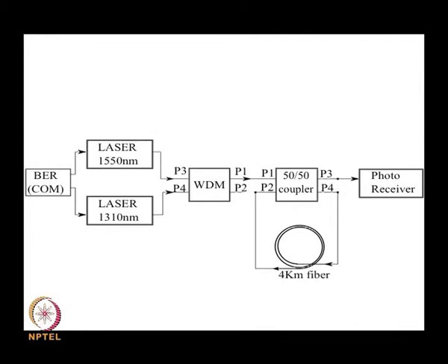The first pulse will be coming directly from the input port 1. The second pulse will be coming from port 2 after travelling 4 km length. Then the third pulse will be coming from the light which has travelled in this resonator twice. So it would have travelled 8 kilometers, and we will get pulses which have travelled larger lengths. The output of port 3 is collected by a photo receiver and the RF output is seen on a CRO. So we will see the dispersion on the CRO.